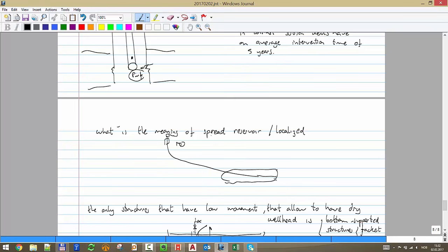So that's what I'm saying, that is relatively close compared to what I can put on top of the offshore structure, what I can afford. I can put a huge drilling package, and I could reach 13 kilometers, for example. But that will be heavier. I need a bigger offshore structure, which will cause more cost to the project. So it's within my limitations. Remember all the time that how I can reach the reservoir depends on my drilling package.